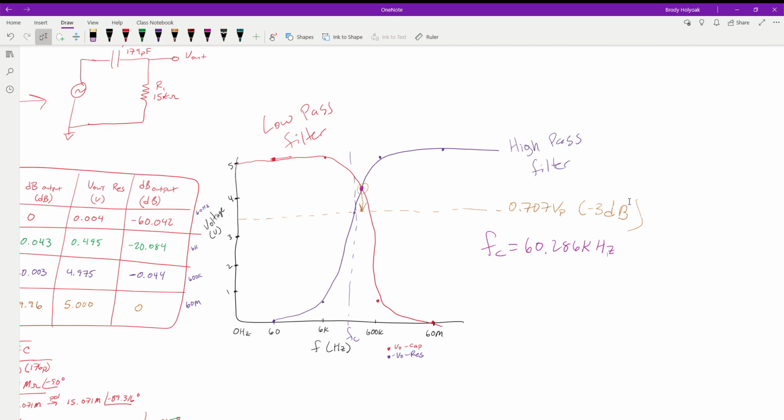Well, now, instead of having to have a single line running from every single tool to give you an indicator when it is done or when it is not, you can have each one of those signals send a different frequency. And then on the receiving end, you can have different indicators that, again, just like with the radio station, are going to filter out every other frequency except for the one you want.